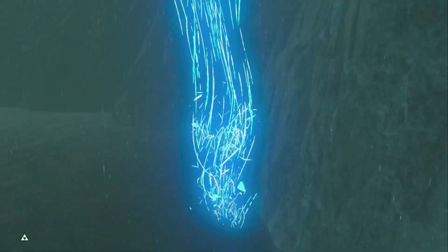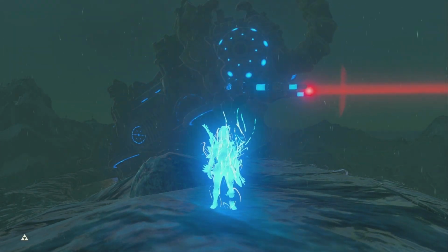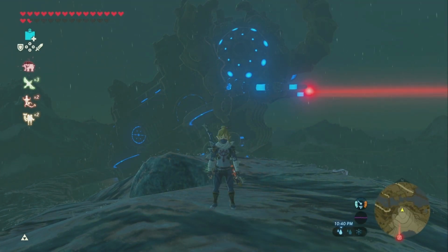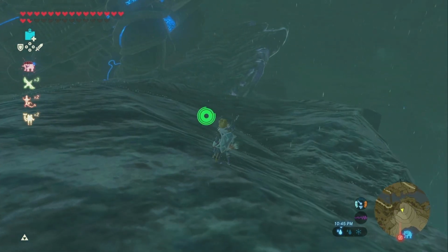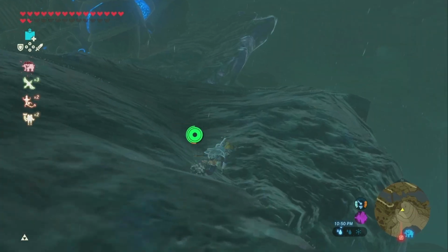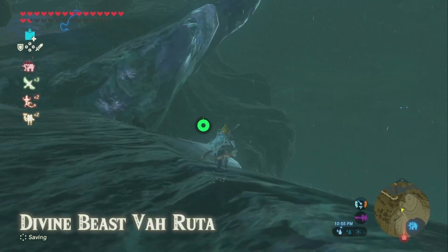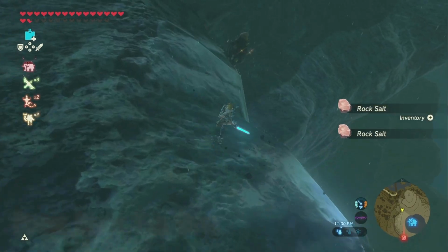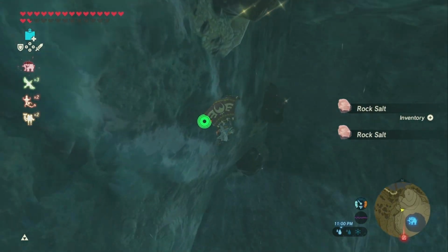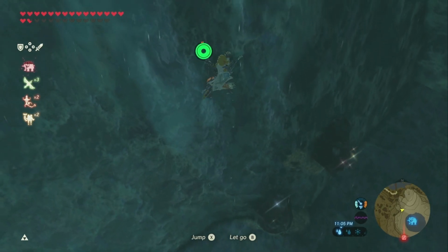Anyways, additional piping needed. With the circulating hot water system, it's not enough to run a supply pipe with hot water to each fixture. There has to be a second return pipe that allows the water to be moved in a loop through the hot water system, or a bypass fitting placed somewhere, usually under a lavatory sink far away from the water heater, that allows the hot water to flow into the cold water line.